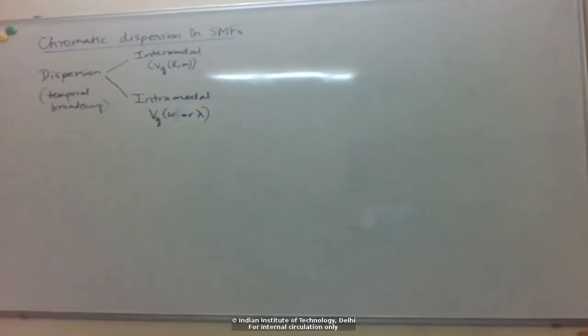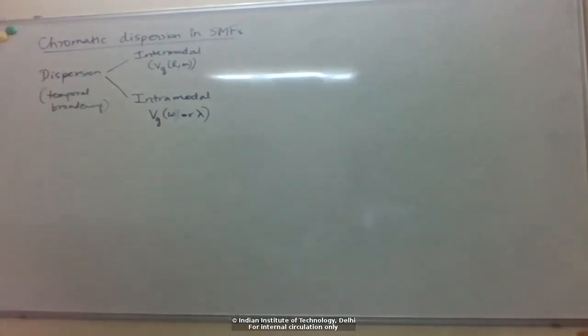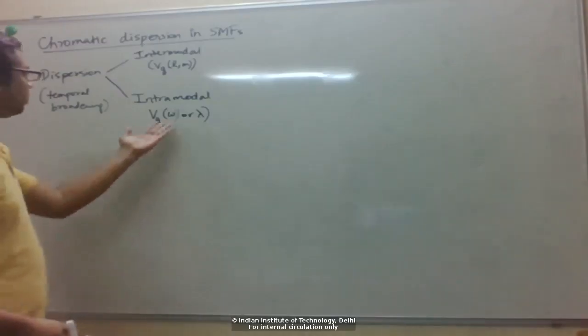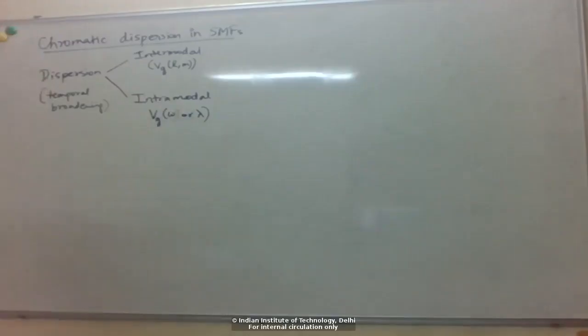Okay. So even though you have only one mode, typically when we send optical pulses, right, you know from Fourier transform relations that any finite extent pulse in time will have some frequency content, given by the Fourier transform. So you'll have a collection of frequencies traveling in the fiber, right, and we'll see that these different frequencies will have different group velocities, which again means that at the receiver, not all the frequency components will arrive together, and that would lead to broadening.